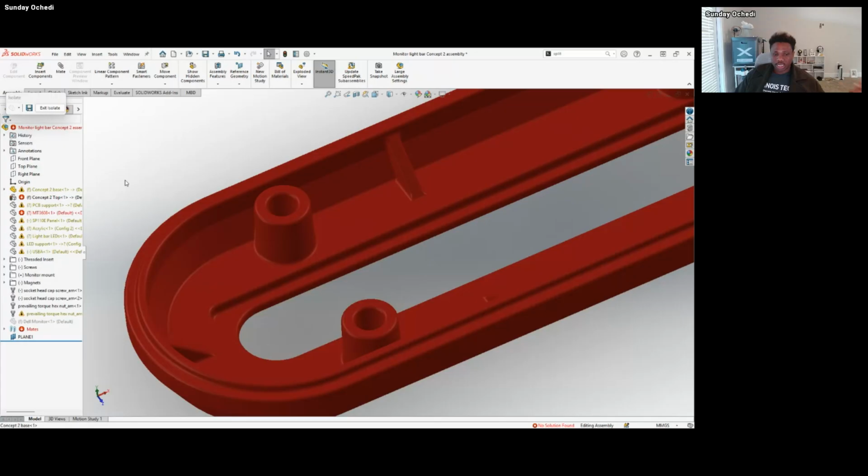If they don't have the tool and you give a tight tolerance, let's say 0.1, it's going to cost you more. Maybe they'll have to buy new tools. Even if they have the tool, a small tolerance like 0.1 will cost you more. It's too tight, and you're giving them no room to make any mistake. So that's what you need to consider: the manufacturing method, what they have in place, and what tolerance actually fits so your parts still go together.